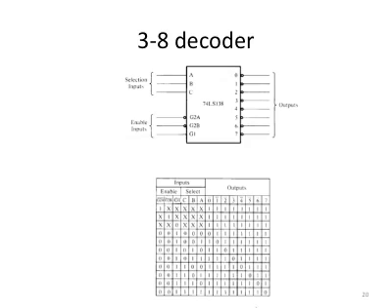And this is the truth table here. From this row all the way to here, this is when we have this chip operating as a decoder. And depending on the input, only one of the outputs is a 0. The rest of the bits are 1s. So that is to say, using this 3-bit input, you can select one of these 8 outputs, and only one.